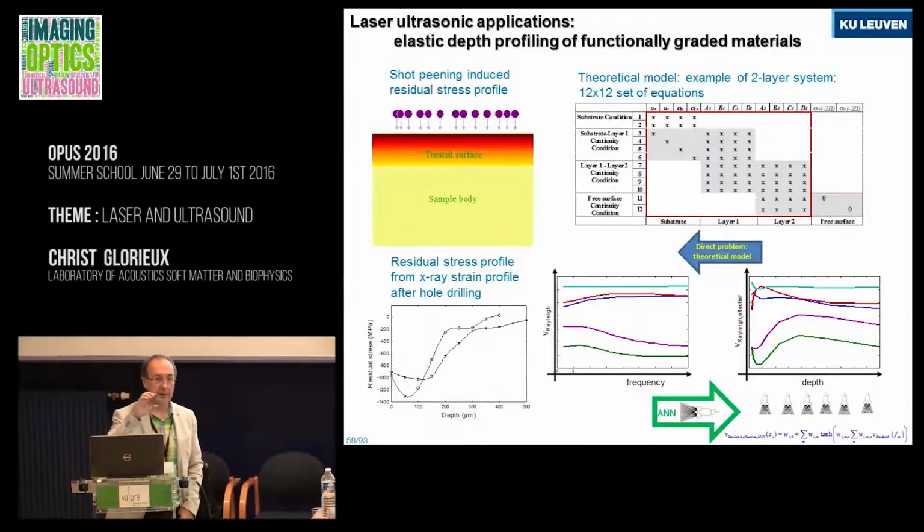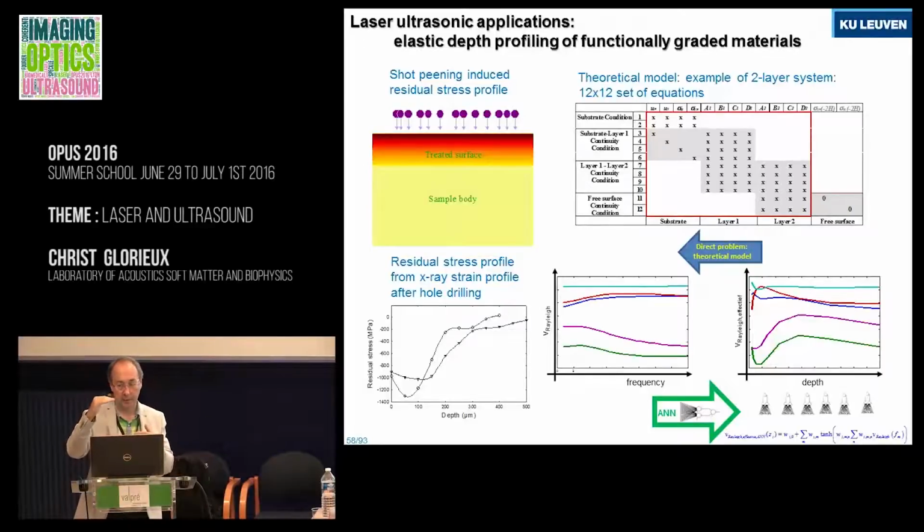Ideally, because of this frequency or wavelength dependent penetration depth of the acoustic waves, you can scan the sample in depth. Yeah? If you have all these frequencies, the dispersion curve can give you the information about the depth dependence of the elastic properties. But you can imagine that if you have such a continuously changing sample, the theory becomes complicated. What we did, we approximated the sample by a multi-layer. We calculated signals. We assumed a lot of possible profiles in the sample.